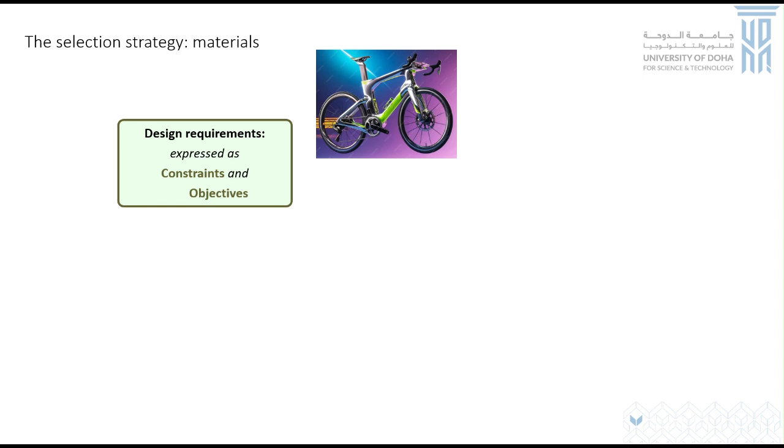So that's why I'm saying it's important to define the function specifically, in terms of the typical words that we use in engineering. From an engineering point of view, this rod is actually a column under compression. When you describe it like that, immediately in your mind those variables should start clicking: it has to have a certain yield strength, the Young's modulus is important, and that's the primary function it is doing. The profile itself can be different, and we can talk about that later.